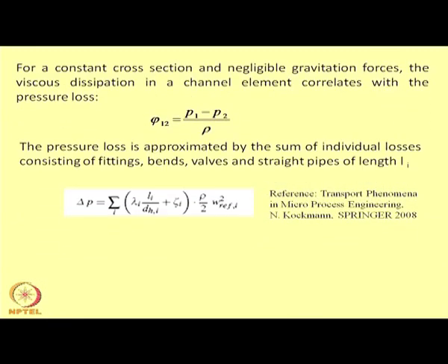The viscous dissipation is incorporated in Bernoulli's equation as an additional term, as a head loss. For the system of our interest, this equation has been provided in the book titled Transport Phenomena in Microprocess Engineering by Kockmann, who has given that the pressure drop for a microchannel with a large number of fittings, bends, valves and straight pipes has two factors.